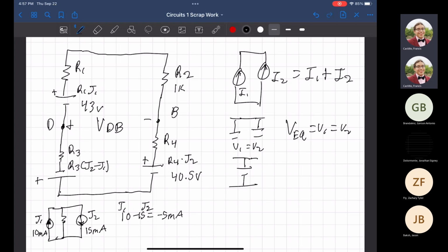Okay, so what's going to happen is I'm going to draw a little line here. I'm only going to combine the top half with itself. So this little network right here, I'm only going to be combining anything that's possible in that, and respectively with this little network down here, same thing. We're going to combine anything in there. Oh, and I forgot to actually show the exact calculation to find our voltage source for resistor 3. That value should be 5 times resistor 3, which is 2k ohms there. So 5 times 2 is going to be 10 volts here.